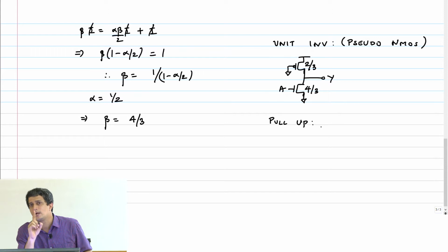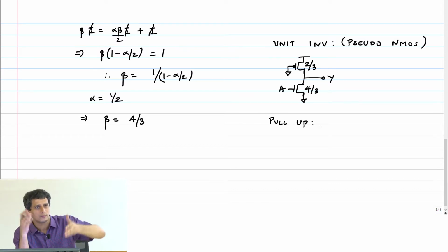Now I'm going to refine my definition. I'm not going to say same drive strength, but rather that can provide the same current to the load capacitor for charging or discharging. Drive strength is slightly vague. You might think it's a resistance. But because of the pseudo NMOS problem, where I have currents from the PMOS also, I'm going to change the logical effort definition slightly to say it is the ratio of gate capacitance compared to a static CMOS inverter which can provide the same current to the load capacitance for charging or discharging.